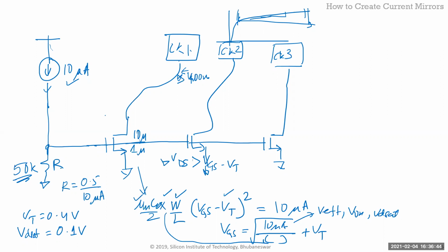But the problem with this is, in theory, this is fine, right? There's no problem with this in theory. What you have said is it works perfectly fine. But in practice, if you're trying to get any kind of accuracy, this will just kill you for a couple of reasons. One is as the temperature varies, the way the resistor varies, the VGS varies, the VTs vary, they're completely different. And you remember, this is a square term here, right? Any gate voltage varying here will make the current vary quite a lot. Same thing, the resistors in ICs, they're plus minus 20%.